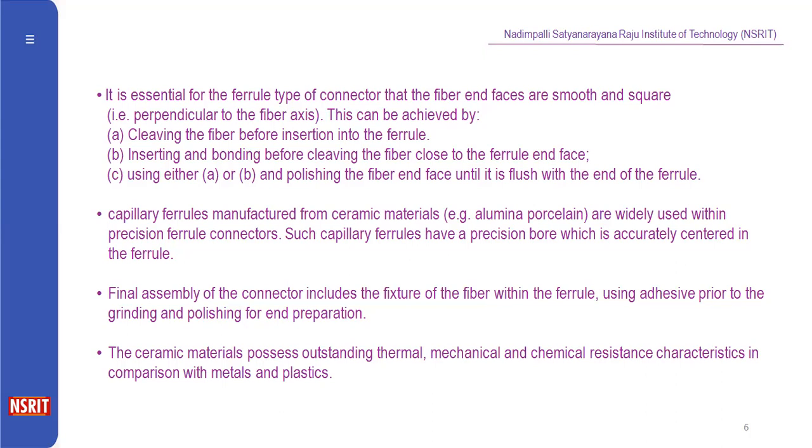Final assembly of the connector includes the fixture of the fiber within the ferrule, using adhesive prior to the grinding and polishing for the end preparation.